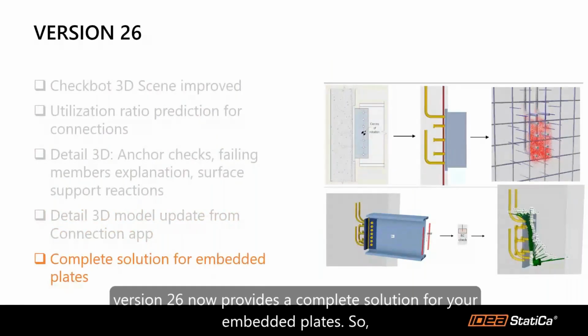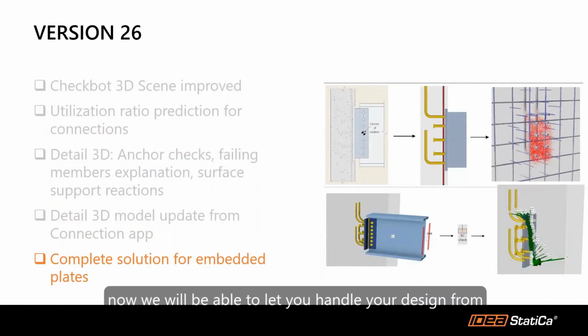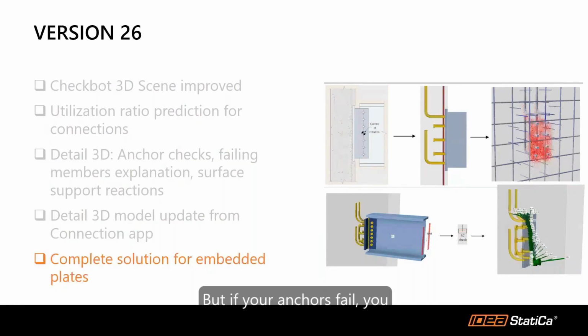And finally, version 26 now provides a complete solution for your embedded plates. So now we will be able to let you handle your design from end to end to be able to have a unified workflow environment. So you could start in the connection application, but if your anchors fail, you now can send your results to Detail to be able to analyze that with reinforced concrete.